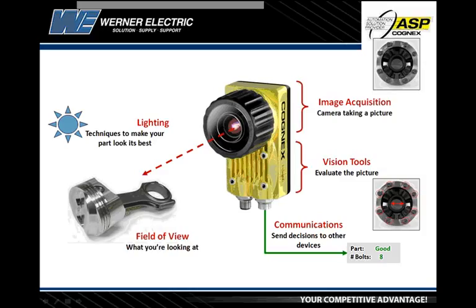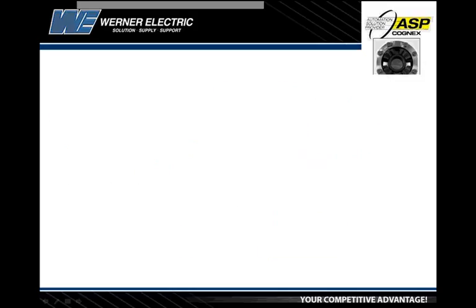If we're looking for defects, we're going to ask for samples of all the different kinds of defects and what we call the worst of the good and the best of the bad. Obviously it's much easier to check defects that are huge than it is to find the subtle ones. So when we're evaluating applications, we want to make sure that we look at the most subtle defect categories.